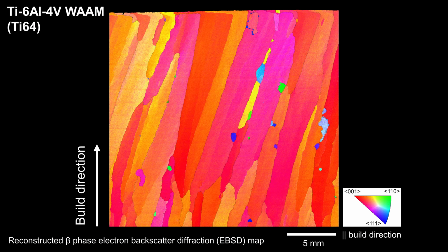Titanium has a further problem though. It just loves solute. It's actually remarkable how reluctant titanium is to forming intermetallic particles with many elements. So, when many titanium alloys solidify, there is next to no solute rejection into the liquid, which means limited undercooling.